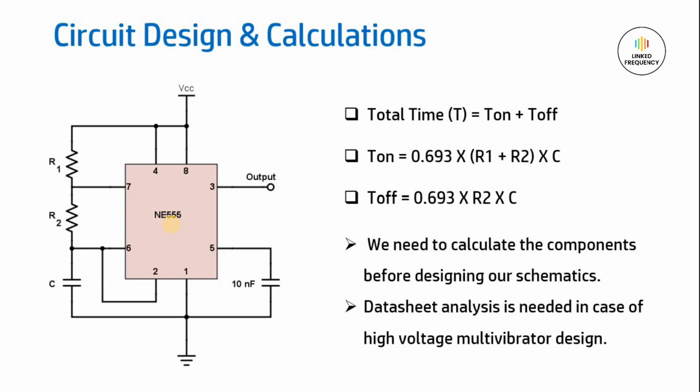First thing is, we need to understand what the circuit diagram for the NE555 timer is, especially for an Astable multivibrator. Because there are two other configurations, monostable and bistable multivibrator design, using the same IC. So make sure that you identify the Astable multivibrator circuit, which is just like this one: R1, R2 resistor and a capacitor and also a decoupling capacitor, all that thing.